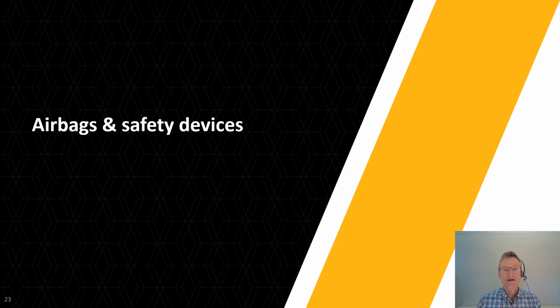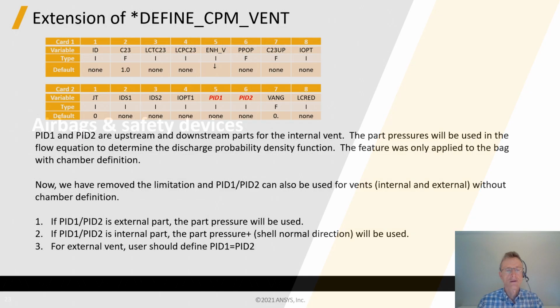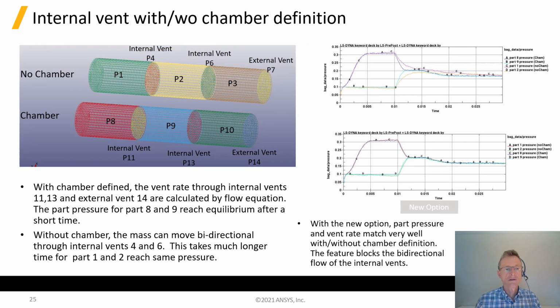The next subject area is airbags and safety devices. So there are some enhancements around the modelling of vents for the corpuscular airbag modelling method. Essentially, the definition of these vents is a bit more flexible now, with the same card being used for internal and external vents. When using this feature to model internal vents, the behavior depends on whether you've created chambers within